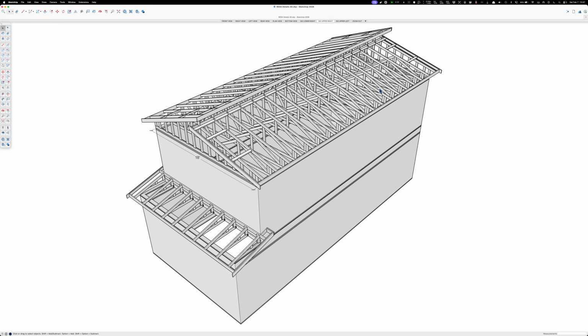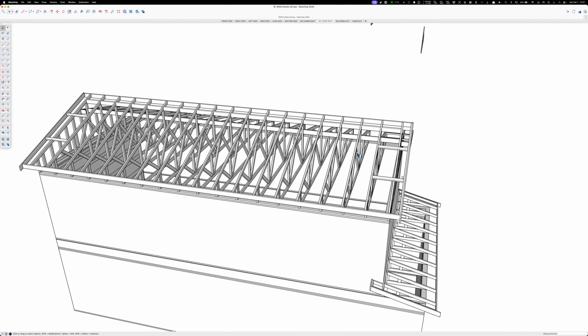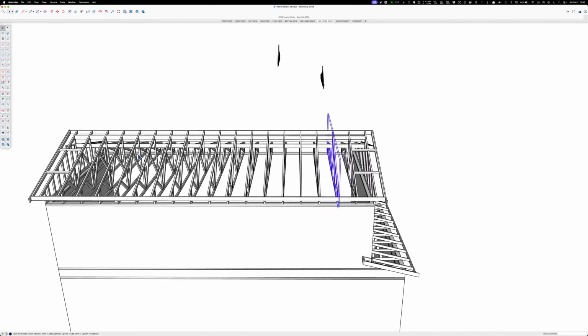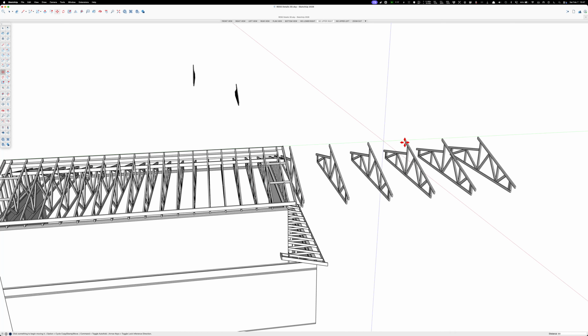And this is where having a 3D mouse is super nice because you can move and get things right. You draw one of these, and then you group it, and then you move paste. Let's do 72, enter, and then you want 6 copies of that, 6x, boom, and there you go.